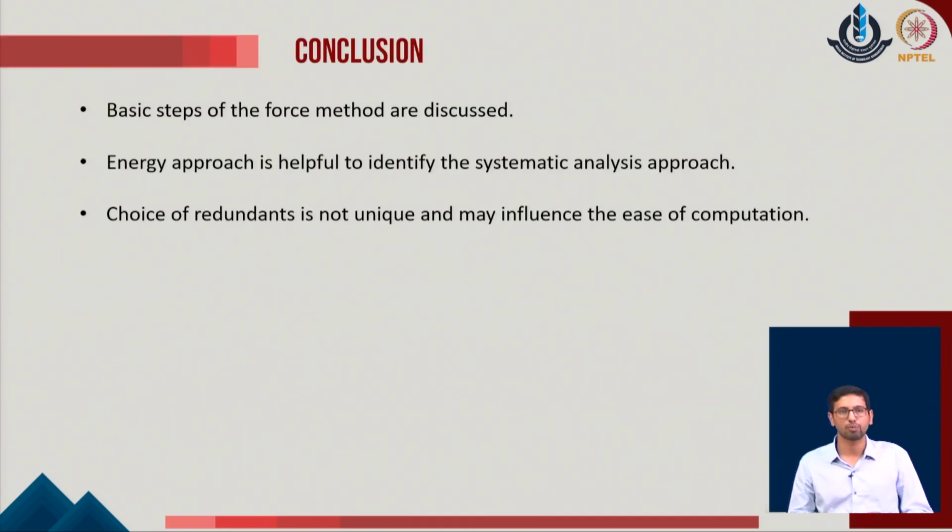So with this we stop over here. We have briefly seen the basic steps of the force method. The energy approach becomes much more helpful to evaluate these sets of deformations. We have seen a systematic approach to define the flexibility coefficients of the given system. And as a rider on the given problem, we understand that the choice of the redundants is not unique, and the ease of computation is much influenced by the choice of the redundants which a user takes.